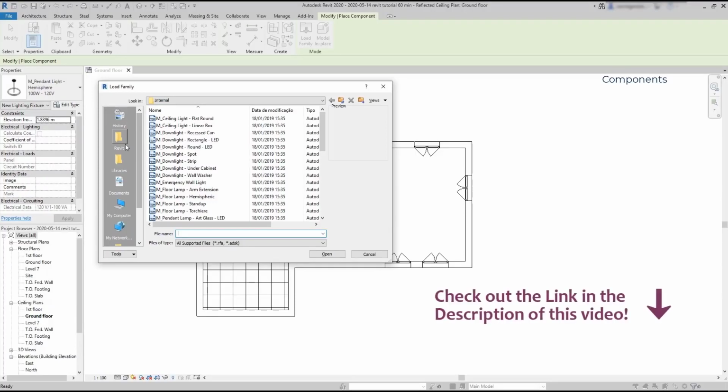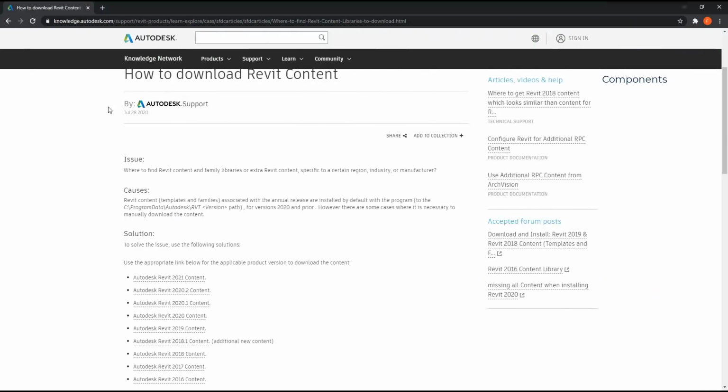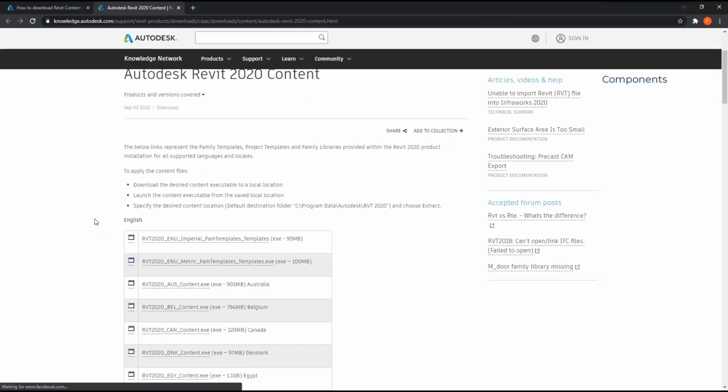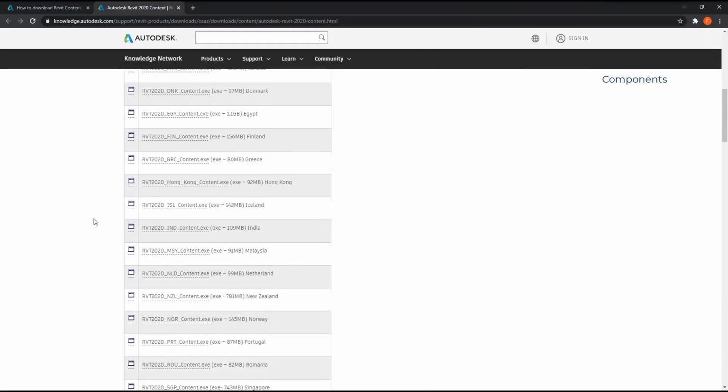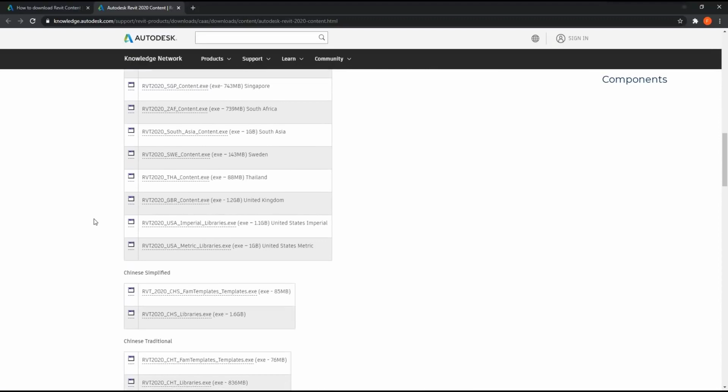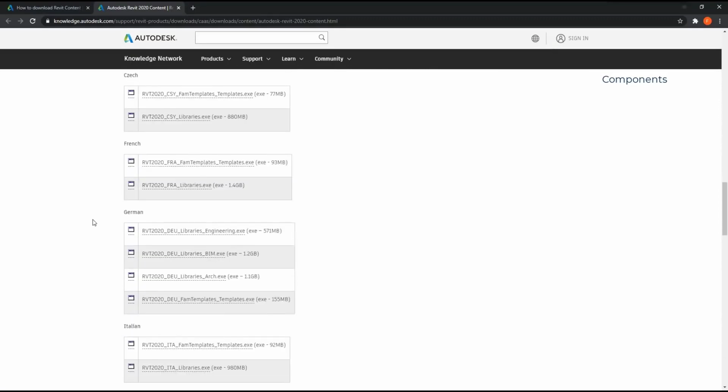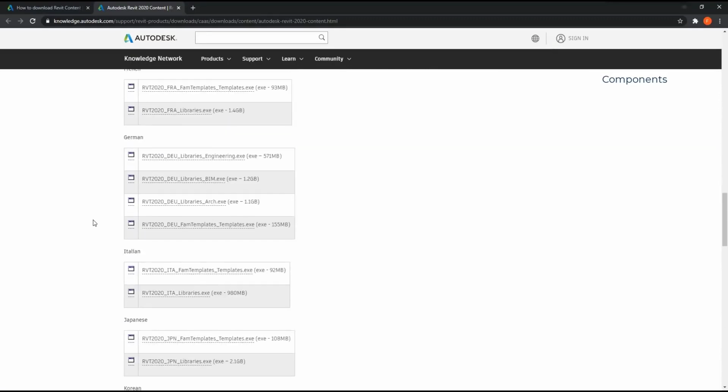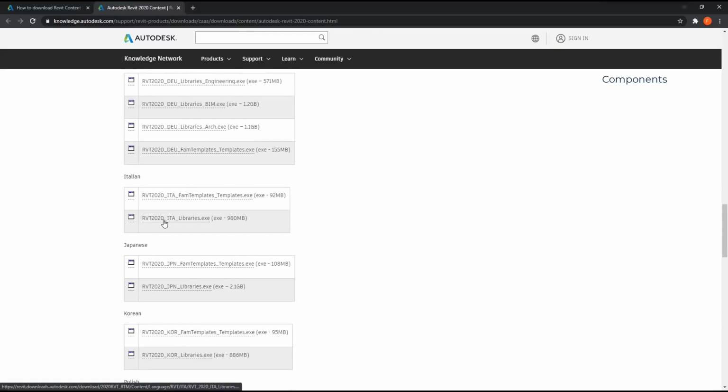I added the link in the description of this video. Click there to access the Autodesk website where you can find the libraries. First, click on your Revit version, search for your language or country, and then install it. They are grouped by languages, countries, or even if they use metric or imperial units. But make sure you click on a library.exe file, like this one, and you will have a very complete library.